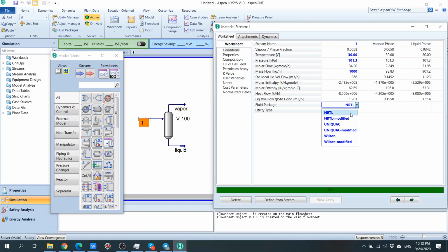And then we do the NRTL modified. So you can see we change this NRTL to NRTL modified. We use these UNIFAC binary interaction parameters. It will then say it's not 6% that goes to the top, it's 15% that goes to the top. So 6 to 15% is a huge difference. It's double.